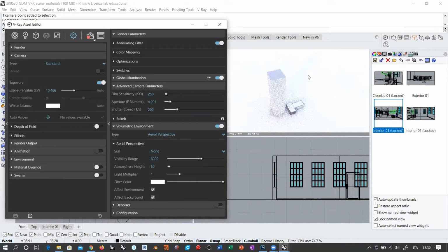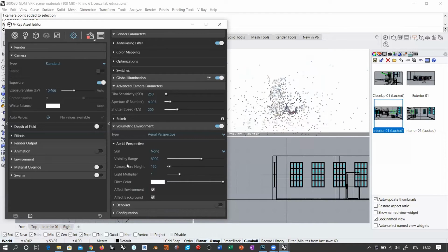And you see that 80 is actually quite a small value for this scene, because 80 is the position of the camera. So there are only 80 meters here where this atmospheric effect can happen. But if I, for example, double this value, then my camera is already inside the volumetric effect. Okay, so we start to have this kind of more or less clear view of the scene.